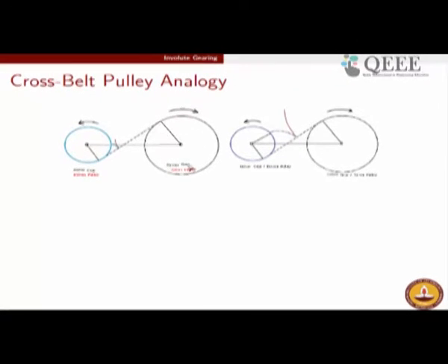Similarly, on the other pulley, if I attach this same piece of paper, what I will see is that on this other pulley, it will generate the involute from the other side, that is, from the smaller pulley it has generated the involute from the circle outwards, whereas with respect to the larger pulley, the involute has been generated from the outer periphery inwards.